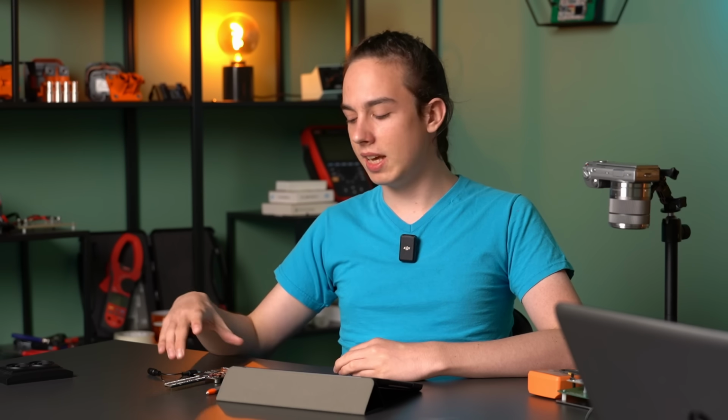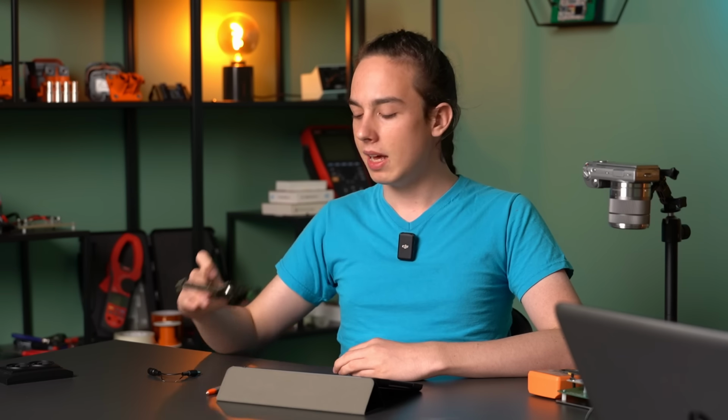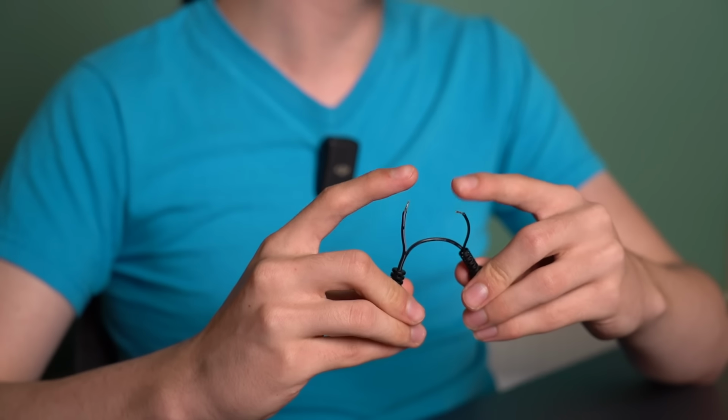For a standard panel, such as the black panel in the written curriculum, this is more complicated than you might think. With the help of this connector, which has one of the power lines disconnected, we can connect the multimeter in series with the current flow and easily measure the total current consumption of the panel. However, this is not enough for us, as we are interested in the power consumption of the microcontroller. Therefore, we need to measure the base consumption of the panel so that we can compare it later.